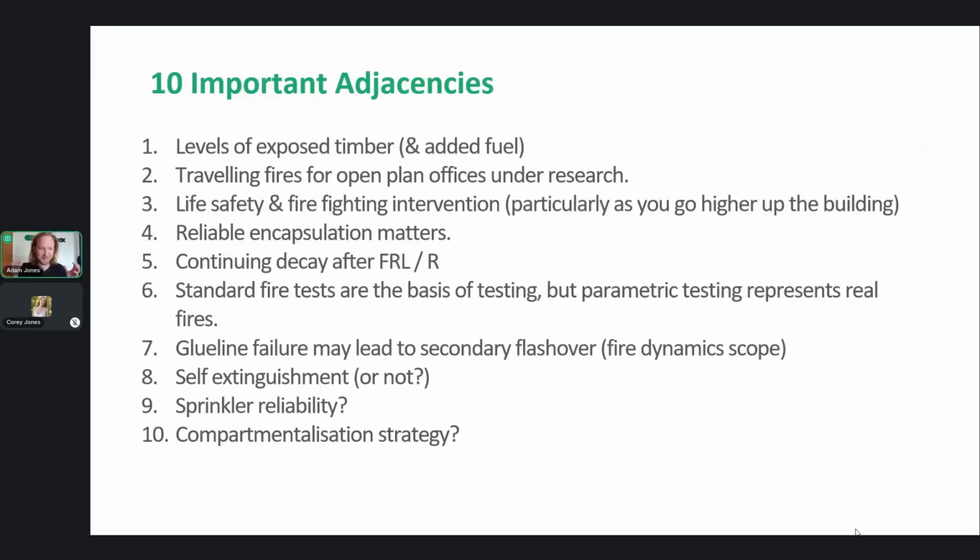All right, so before we get into it, I think it's always good to start at the very high level, some of the topics and the breadth of topics that come up. And a lot of these, or most of these, we're not addressing in detail today. So when it comes to structural fire design of timber buildings, you got to think sometimes about the levels of exposed timber and added fuel. So do you have multiple surfaces exposed onto each other, and how does that add fuel to the fire? Travelling fires for open plan offices is under research, and sometimes the testing doesn't cover the cases of open plan offices. There's consideration to life safety and firefighting intervention strategies.